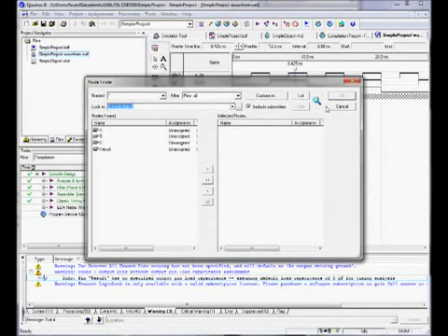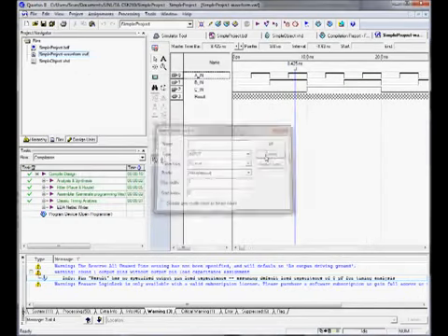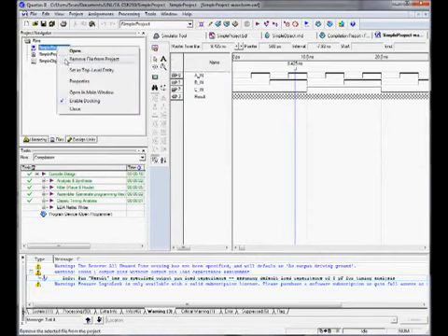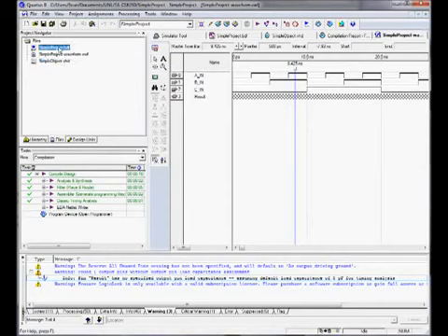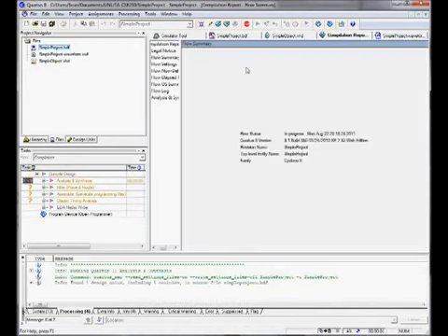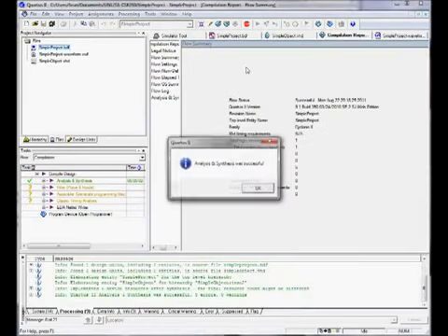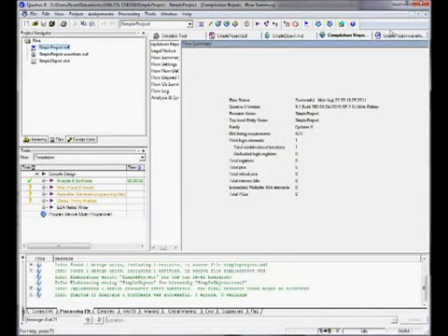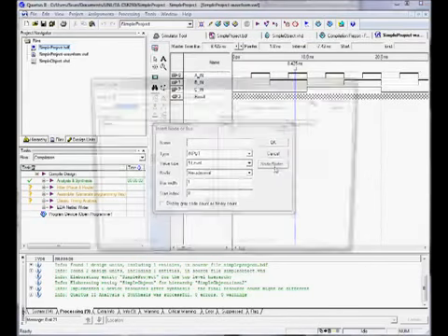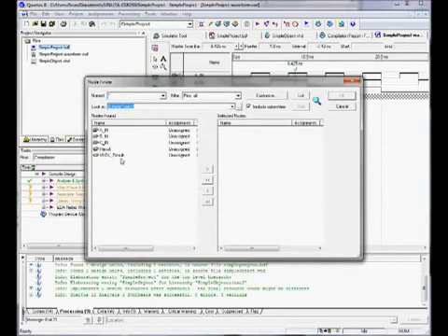Again, it caught me. Because I compiled that and this wasn't the top level entity, it was compiling our simple object VHD. So we'll go back to him, make him the top level, and try again. And I will apologize for wasting a minute and a half of your time on that. Okay, so now we're good to go. We'll come back once again into our waveform, insert node or bus, find the node, list everything. Haha, there we go. Click on him and put him into the result.